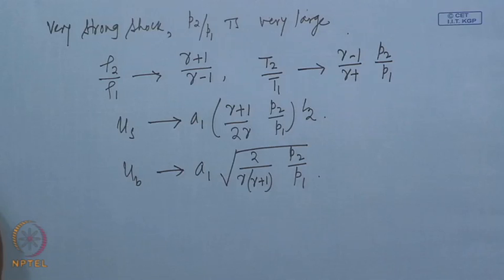We have also found the limiting values for the density, pressure and temperature rises, as well as the shock speed and the flow velocity behind the shock. What we have seen particularly today is that a moving shock or a disturbance sets the fluid in motion. However, how this motion develops is what we will try to see next in our next lecture. Thank you.